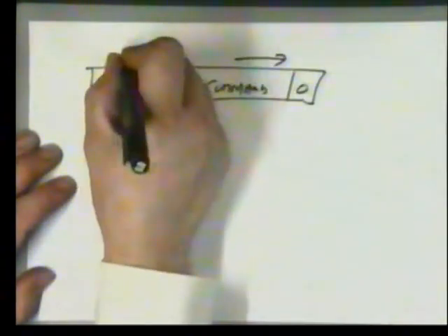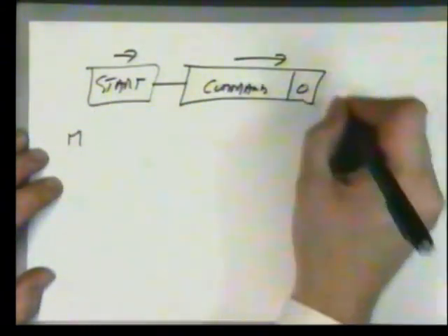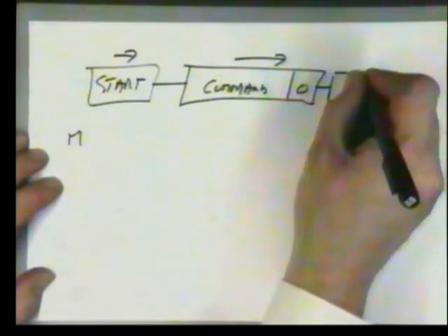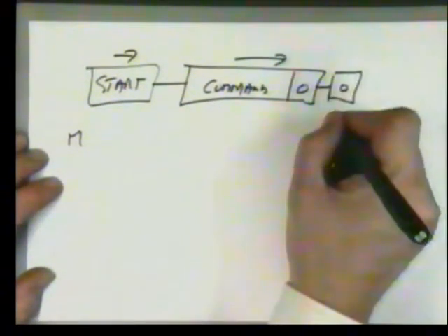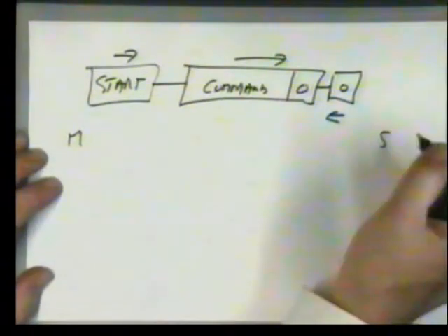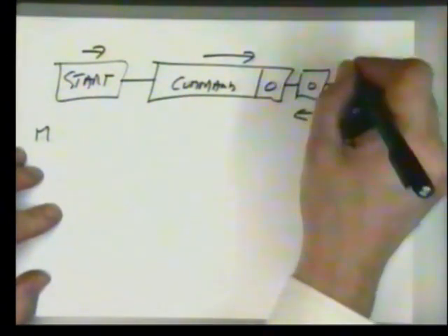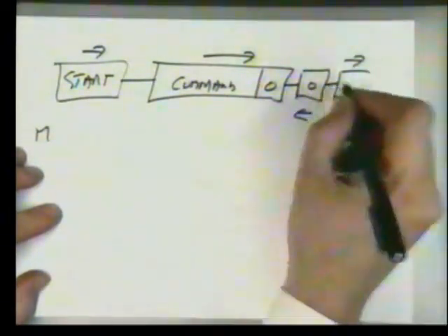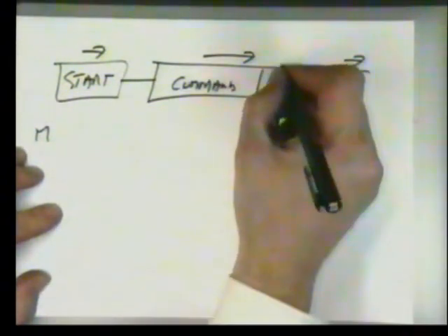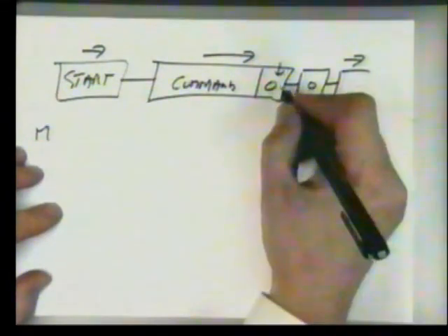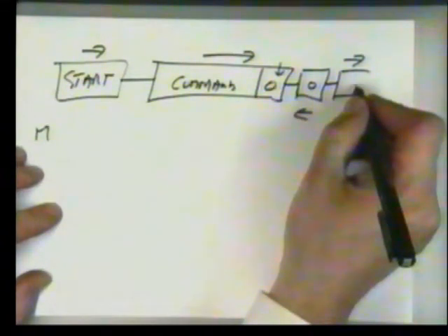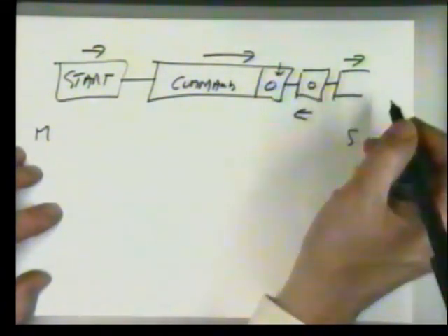That goes out, master to slave. The slave acknowledges by transmitting back just 1 bit, a 0. And now the next command will then follow on master to slave, because it's the least significant bit that tells us whether the next transfer will be master to slave or slave to master. So that's how that's done.